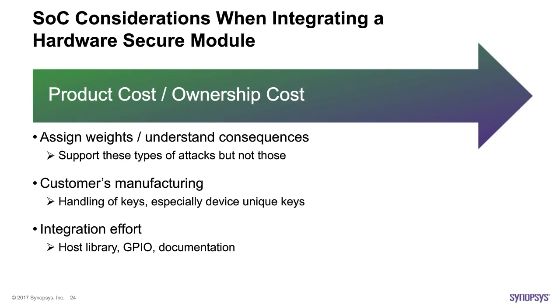So the challenge becomes now, how do you provision them on a chip-by-chip basis? Who on the floor has access to these keys, and how do you prevent leaks? It's an additional cost that they'll need to consider when supporting this. Other items that need consideration include when a customer wants to use their HSM. This is the one that they store their information in. How can you protect and integrate that flow? Will their certificate authority or CA require tools from you? And if so, how do you pass that sensitive information, like key material, from the CA to the person responsible for integrating the hardware security IP? All these flows need to be addressed in some manner.